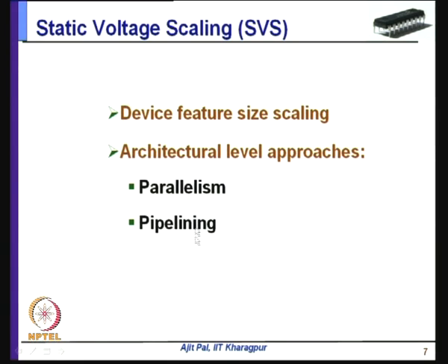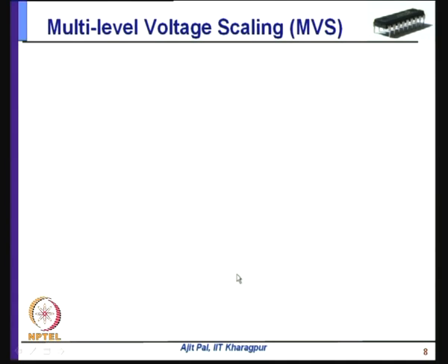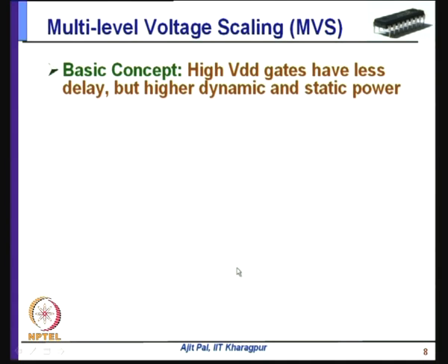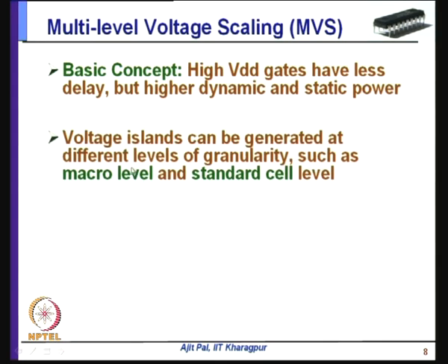So, these are the static voltage scaling approaches, and these are decided at design time, as I have mentioned. Then comes multi-level voltage scaling, and here again the basic concept is high VDD gates have less delay, but higher dynamic and static power. What can be done? Voltage islands can be generated at different levels of granularity, such as macro level or standard cell level. So, we can create islands of circuits at different levels of granularity.